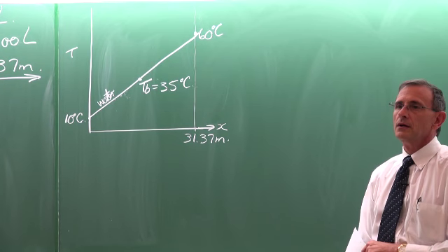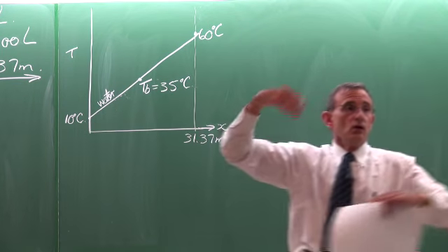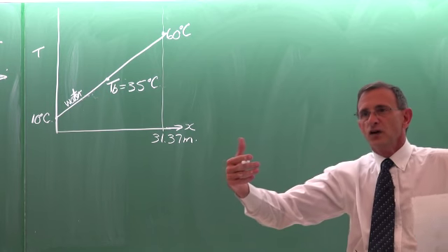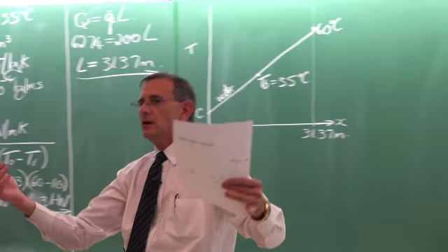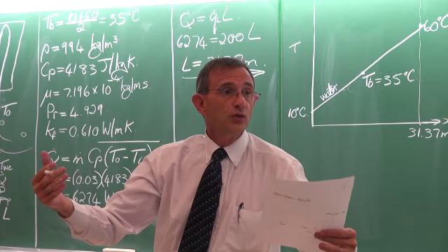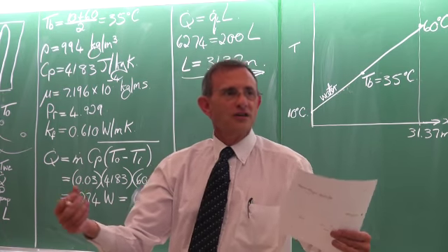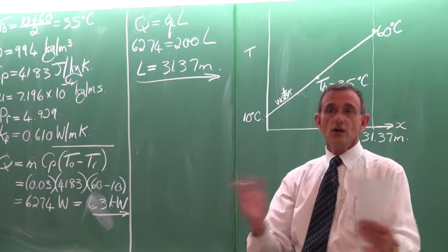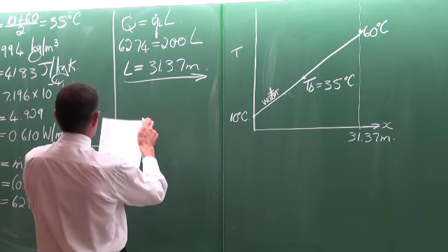Okay? Right. Now we have to go and get the surface temperature. Therefore, we need the heat transfer coefficient. To get the heat transfer coefficient, always the first thing we have to make a choice between is: is the flow laminar or turbulent? So the obvious thing to firstly do is to go and calculate the Reynolds number so that we know in which range we are.